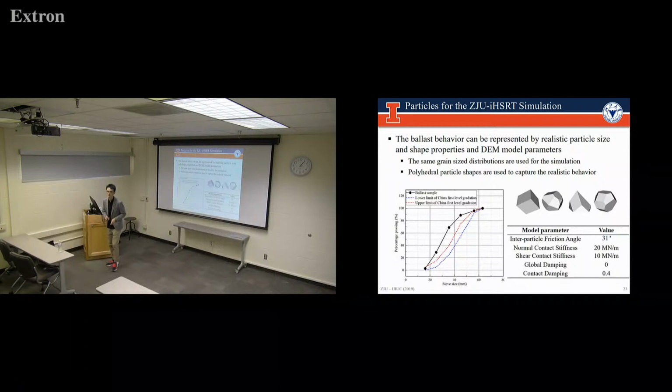Thank you. What do you use as a support for the ballast, underneath the ballast? What's the condition that you put for boundaries? So in DEM, it's a totally rigid boundary. And how accurate is that? I mean, what would the impact be if you put, for example, a certain condition, maybe the simplest one can be springs, like a spring foundation. So it would be difficult for us to have springs underneath. Just one example, but yeah, how is the impact of assuming that you have rigidity, especially if you have weak subgrade or weak soil?